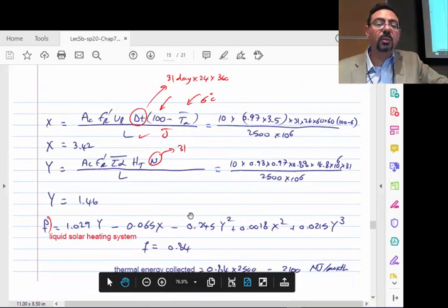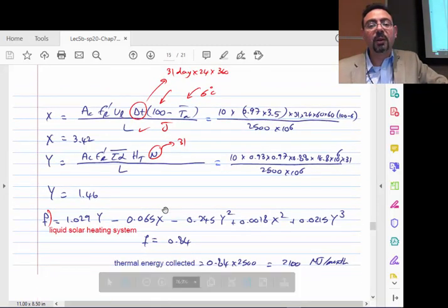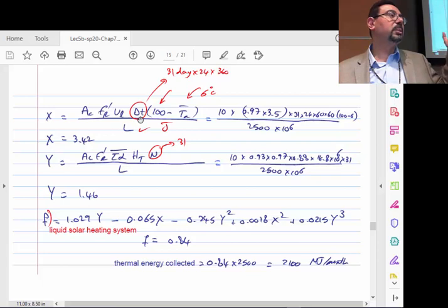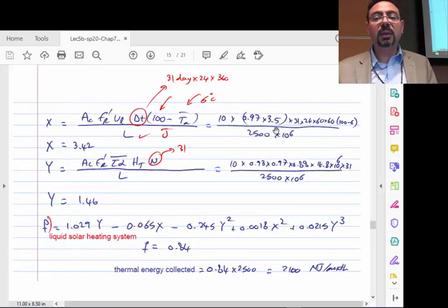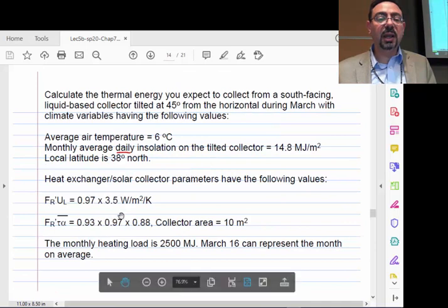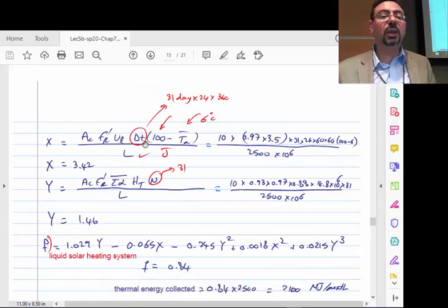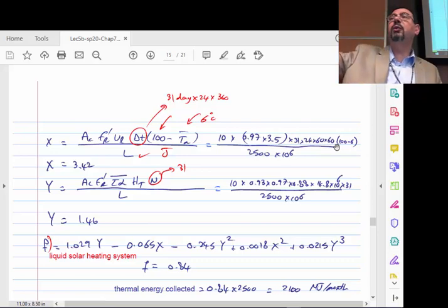You can follow those numbers at your leisure at home. And you will be able to see what the trick is: the units. Look at this, the delta T, the number of hours per month. But since he gave me watt per meter square, my problem now is the UL is joule per second, so I need to multiply by seconds. That is the seconds in the month: 31 times 24 times 60 times 60. 31 days, 24 hours, 60 minutes, 60 seconds.